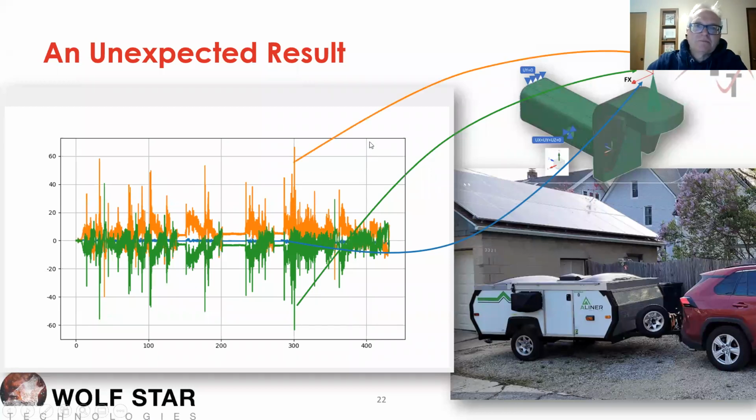And then the FY load. Okay, so this is the counterintuitive piece here, right? Because all of us from our mechanical engineering, when we'd sit down and do a load calculation on this trailer hitch, we'd look at the CG of the trailer, gravity, and we'd calculate a downward load on the trailer hitch. And there is downward load on the trailer hitch, but what's happening is we're getting a lot of upward load.